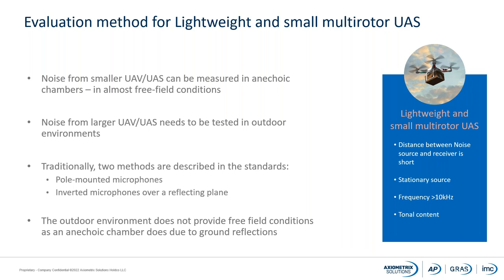And the reason why is, of course, safety issues, because you don't want to have a very big drone in an anechoic chamber. And that goes also for some of the smaller UAVs, UAS. And therefore, you are basically forced to be outdoors to do the measurements. And then you have the issues with the reflecting plane.